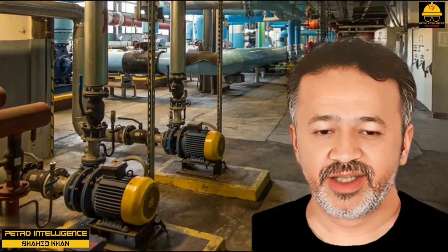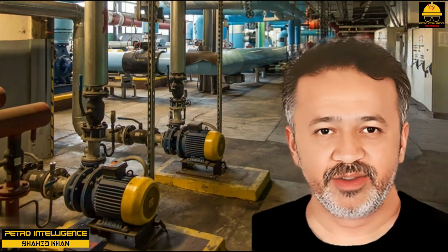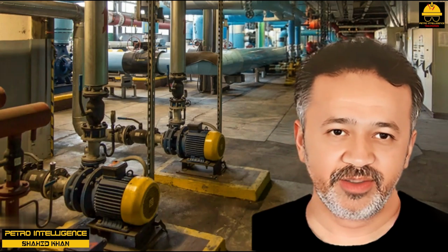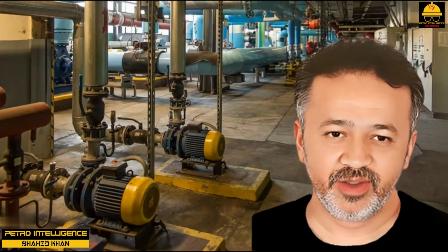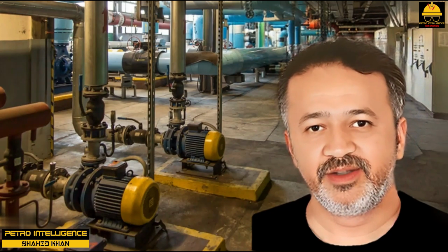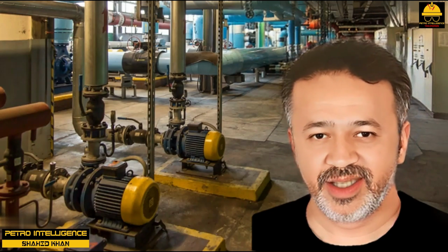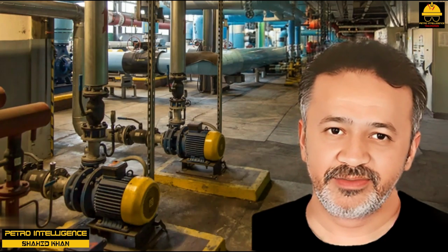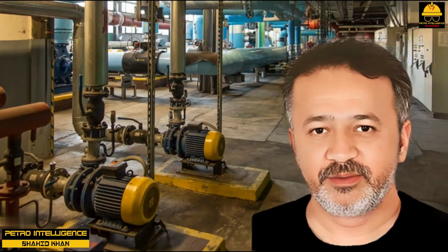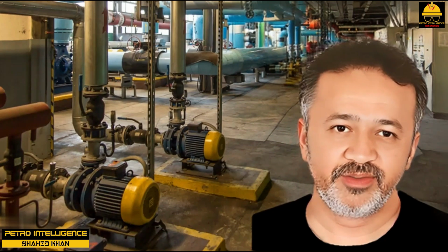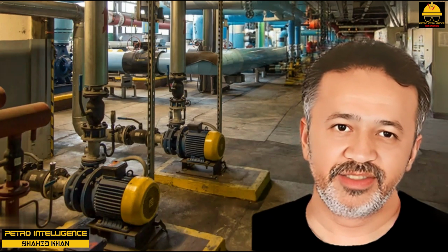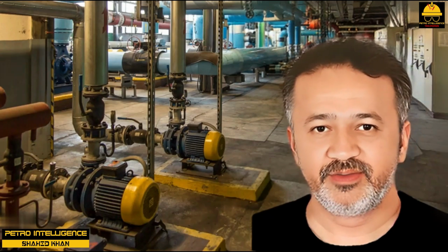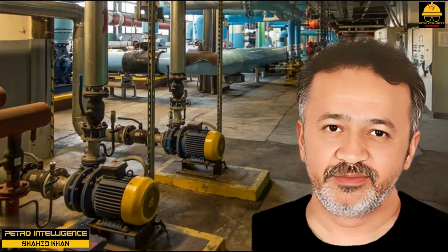Even though the governor steam speed control valve is wide open, the reduction in downstream pressure in the steam chest will increase the steam flow into the turbine. Of course, increasing the motive steam pressure will greatly increase the horsepower available to the turbine. First, more work can be extracted from each pound of the motive steam, and second, increasing the steam pressure will increase the pounds of steam flowing through the governor.